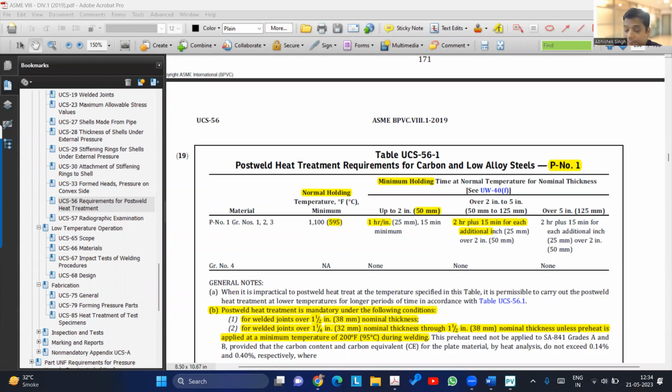So when we were talking about the radiography RT1, RT2, we have weld categorization A, B, C, D. Correct. So in RT2, we were taking A and D in one part, that is the full radiography for RT2, and B and C for the spot radiography. So is there some thought in the code on why they have combined A and D together and B and C together? Yeah, definitely. I'll tell you. It's a very good question, actually.